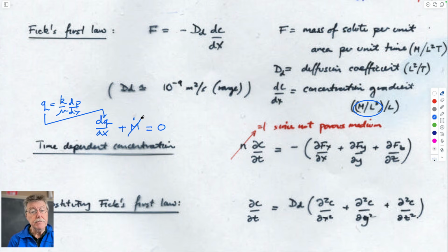This was the term that became the accumulation. So that's exactly what we do here. Instead, we take Fick's law. I'm not going to use these equations. In terms of a mass flux, this is a fluid flux, which is equal to, I guess we need the minus sign in here, minus diffusion coefficient, concentration gradient.